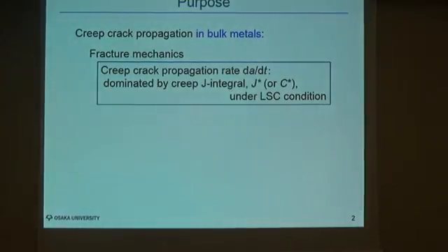And fracture mechanics is often used to characterize the creep crack propagation properties in bulk material. Many experimental studies have confirmed that the creep J integral, J star, often called the C star integral, is a dominant fracture mechanics parameter of creep crack propagation, da/dt, in the large-scale creep condition.